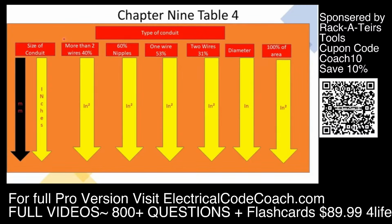The first one that we come to is when we have more than 2 wires. So anytime we have 3 or more wires, we're going to use this percentage. It's the 40% fill column. What it's saying is you're allowed to fill that conduit up to 40% of its capacity. And these values listed down below are going to let you know what that capacity is. So we'd start here on the left-hand side, find our trade size conduit, and then we would come over to our respective column, and that lets us know the total square inch capacity of this pipe that we are allowed to fill. In box fill, we use cubic inches, but in pipe fill, we're going to use square inches.